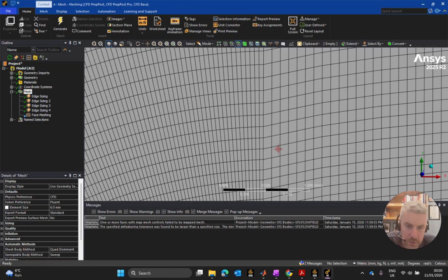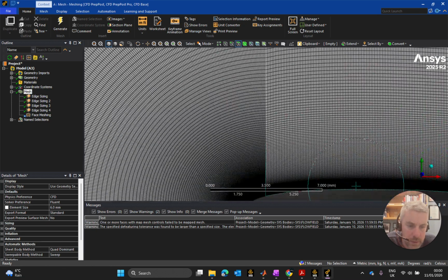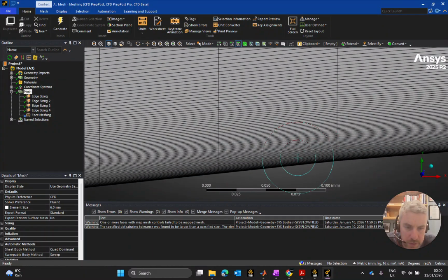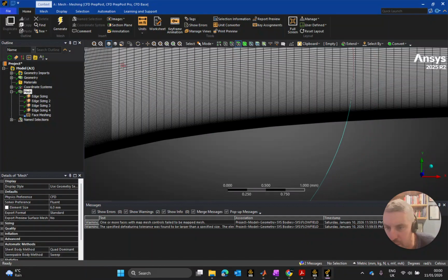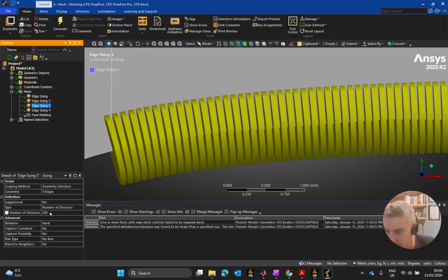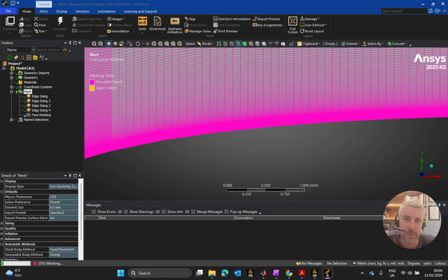This is getting longer, so I can put in more divisions that way, which I was thinking about doing anyway to deal with the very out of whack aspect ratios here. If I cut them in half, that would solve that, and that would also bring that a wee bit closer. So just for the fun of it, I'm going to put that up to 480 divisions. It's not really solid to be able to do that. I'm just putting in more computational effort onto this.